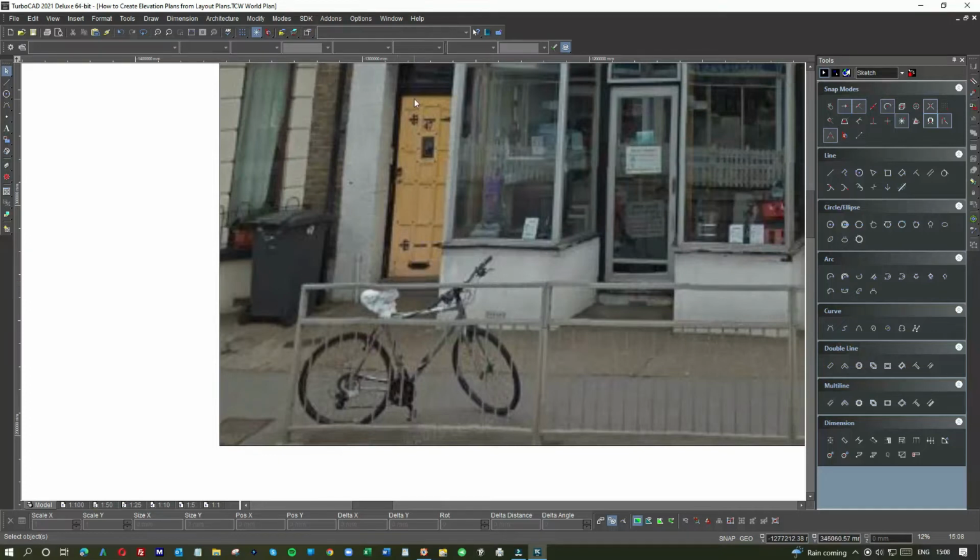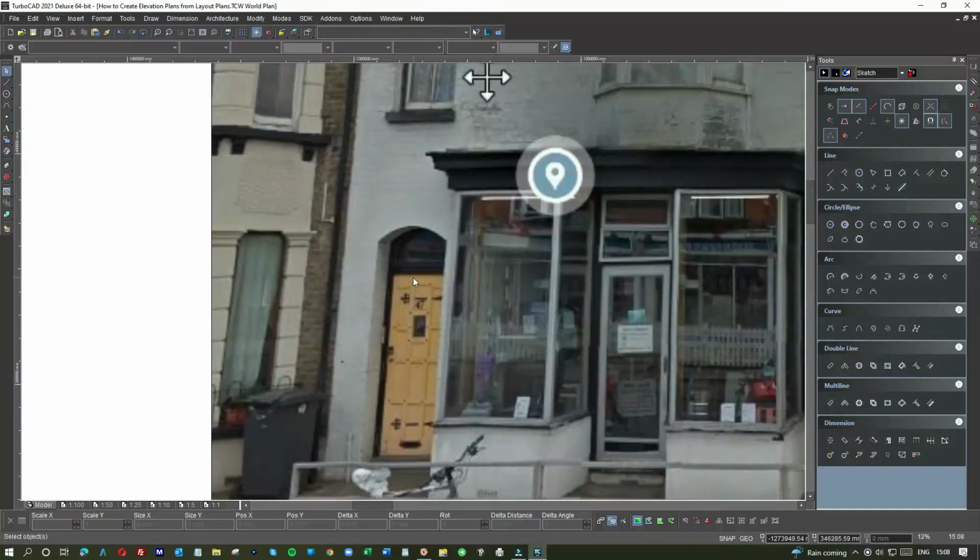Then we've got a reasonably standard door, about 2000 mil. So that's 2000 for the door, 300 for the step. Then we've got a fan light above, which is curved, looking about 500, plus the thickness of the frame. So let's say 600. And then we have bricks.